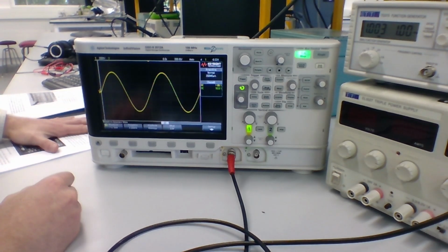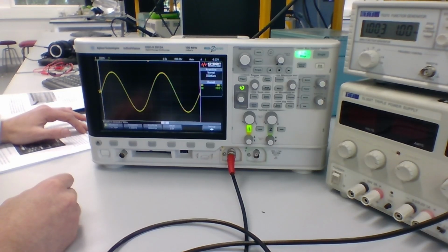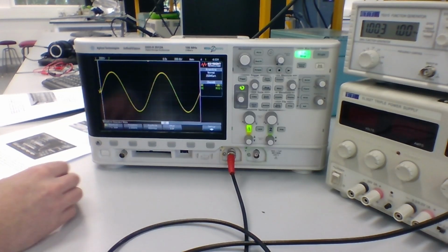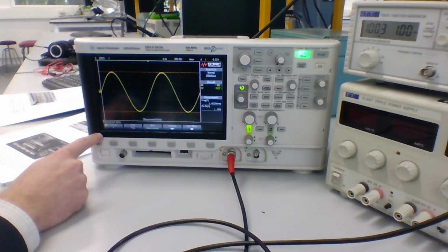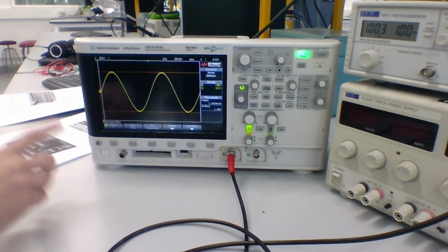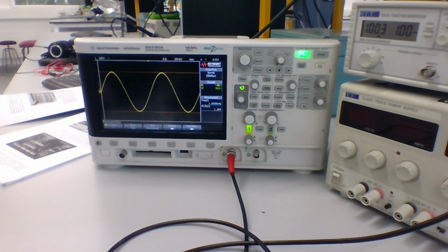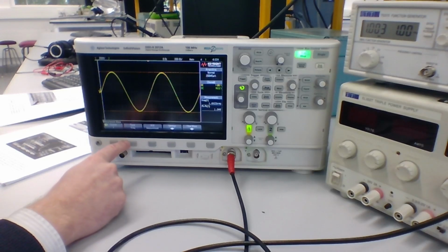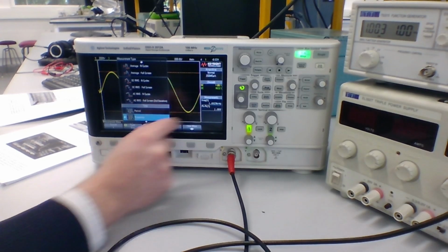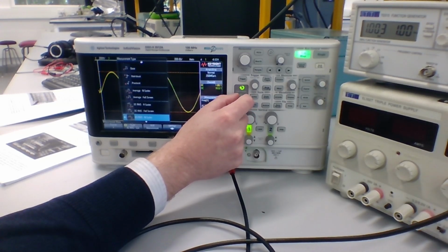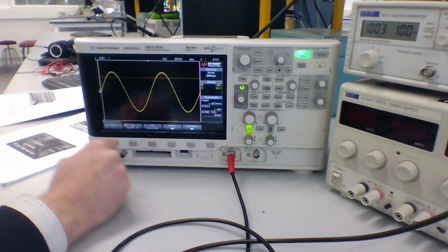Then, following the instructions in the lab manual, rather than measuring with the cursors or the divisions on screen, we're going to use the measurement menu. So, following through that, we're going to press measurement. Make sure source 1 is selected, so we're measuring what's on channel 1. And we want to measure the frequency and the peak-to-peak voltage as well. Currently, these are set up on the oscilloscope. If we wanted to change those, we'd press the type button and use the dial to select what type of measurement we want. Let's say we wanted to know the DC RMS, for example. We then press the button to add that measurement.